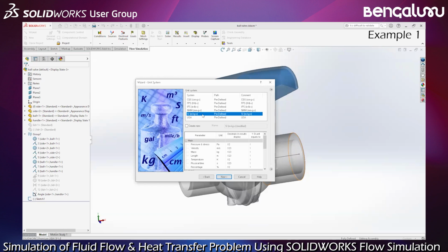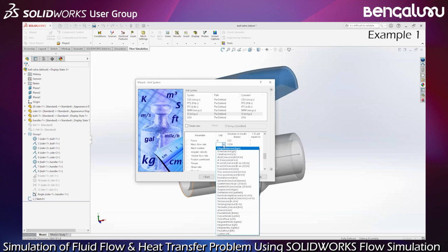And even if I have selected this, I can say, okay, I would like to deal with the SI system, but for example, for temperature, if I have to use temperature, I would like to use Celsius, and some other values, okay? For example, for flow rate, the mass flow rate, I can select from a given list, but you can have your own list.